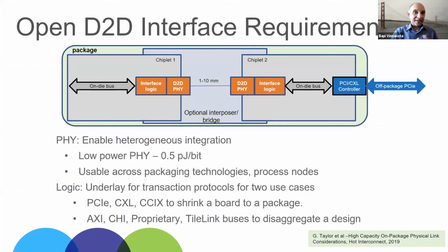But let's say I have a chip with a bunch of wires interface and I needed to talk to an interface with an AIB. That's a discussion we're beginning, but there's no formulaic answer for that. There's no well thought out answer for that, right? So fundamentally, a lot comes down to two big things. If I'm a chip designer, system designer, I want to live and reuse the protocols I'm familiar with. I don't want to go out and use a new protocol for my system. I want to use PCIe, CXL, C6, or AXI, or CHI, whatever it is that I'm using for that.